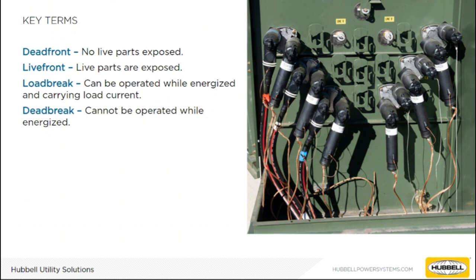From there, cable accessories can be classified by dead break and load break. Load break products can be operated while the cable is energized and carrying load current. Dead break products can only be operated when the cable is de-energized.